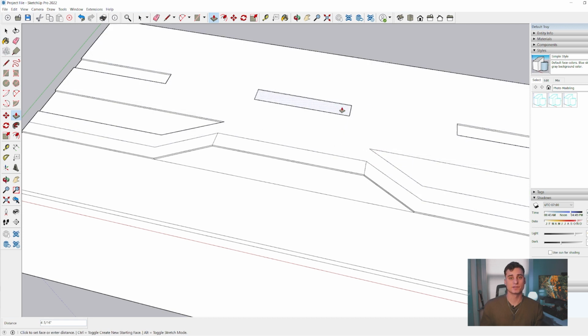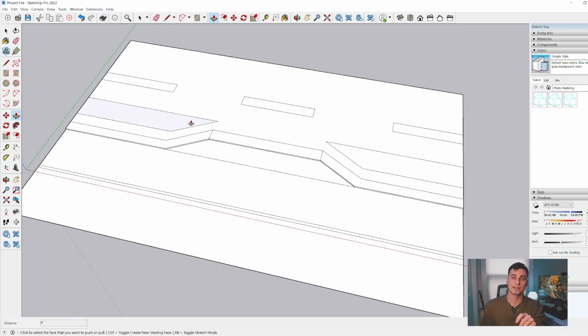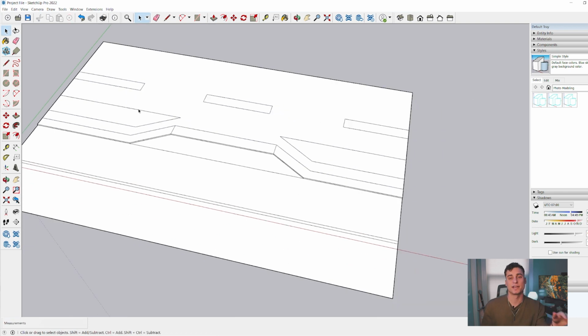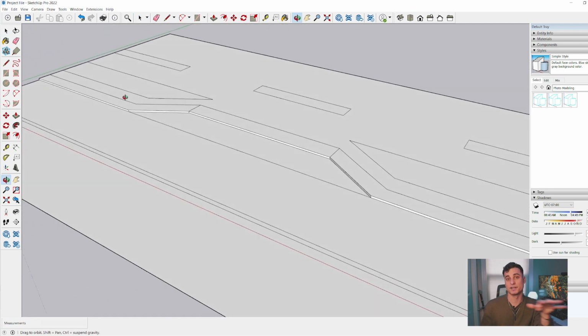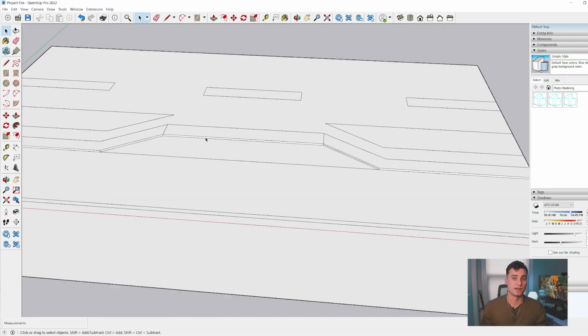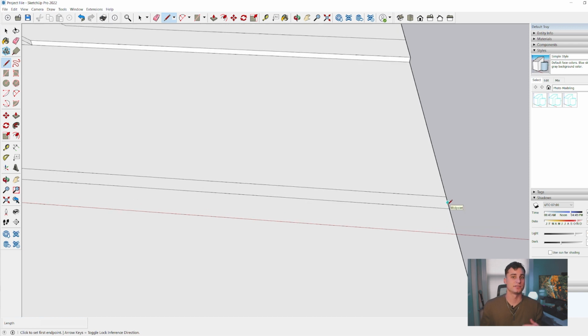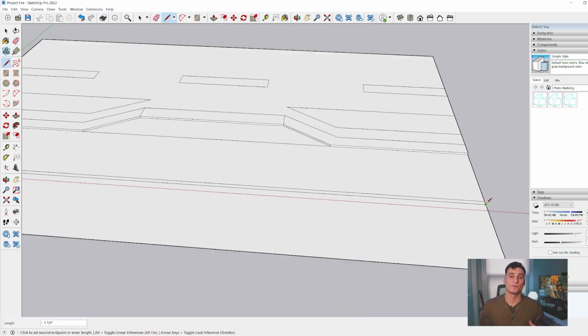Now with SketchUp, you can either continue typing in 6 inches every time, or you can click and drag and highlight to an area that's already 6 inches on the top of that face, and it will bring that face you're manipulating to the top point of that one as well. But once you have that all set, let's go ahead and start to draw in some of the details for the planters and for that ramp.